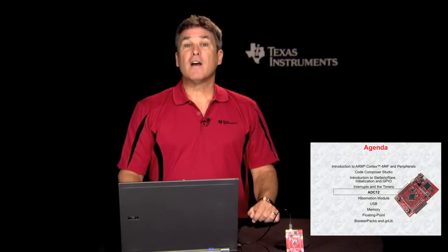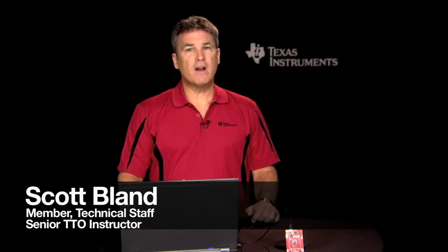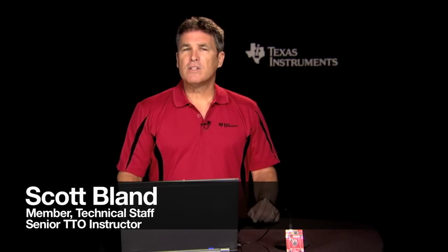Chapter 5 covers the 12-bit analog to digital converter, or ADC12. The LM4F120H5QR has two of them. Since most microcontroller projects measure and/or control things in the real analog world, the device needs to be able to monitor what's happening out there. One channel of the ADC12 is connected to an internal temperature sensor. You'll use that sensor in the lab to monitor the temperature of the LM4F120H5QR and experiment with the ADC12.